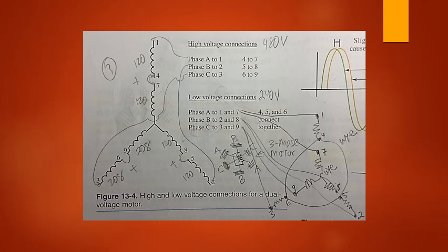The exact RPM of the rotor is dependent on the number and size of the rotor bars embedded in the rotor. When the motor is loaded with a heavy mechanical load, the rotor slows down and the percentage of slip increases. As the slip increases, a greater current circulates in the rotor circuit, which then produces a greater torque.